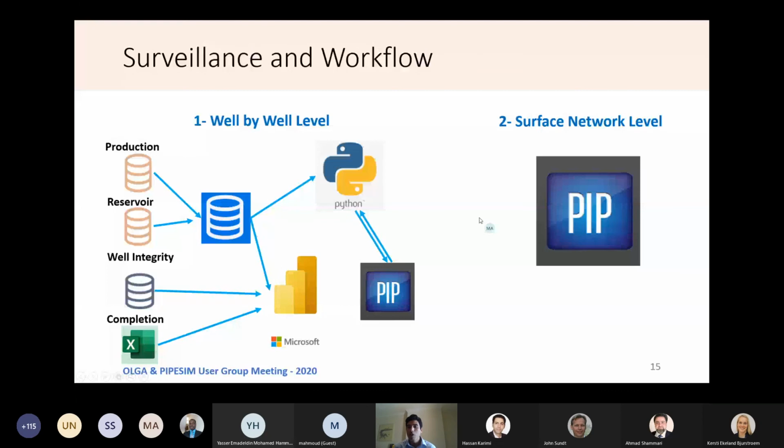The surveillance was directed toward investigating the liquid loading wells in a customized way through an in-house developed code that integrates production and reservoir data. The aim of the tool was to provide customized production performance analysis at well level for all wells in the field, around 80 wells.